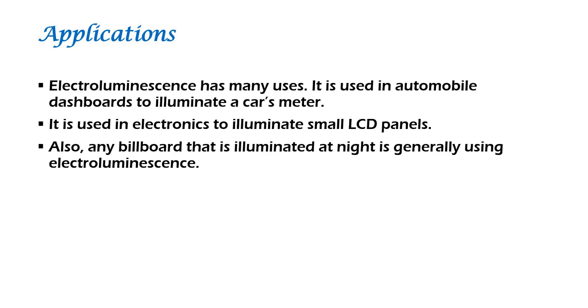Electroluminescent wire or cable is constructed with a thick inner wire surrounded by a coating of light emitting phosphor, and around this is wrapped a very fine outer wire. An outer clear plastic jacket or sheath protects the chemicals and insulates the voltages on the wire from external leakage.